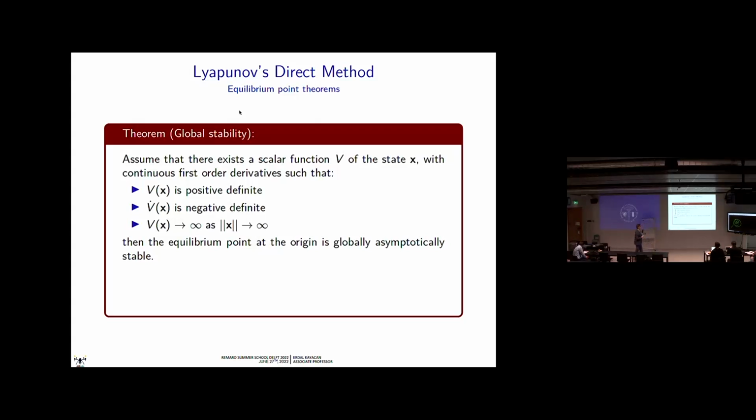Okay, global stability. And if the derivative of V of x is locally negative definite, then the stability is asymptotic. So when I say V dot x is negative definite, not semi-definite, but negative definite, then I can say the stability is asymptotic stability, not Lyapunov stability. Because it could be smaller or equal, or it could be smaller, right?